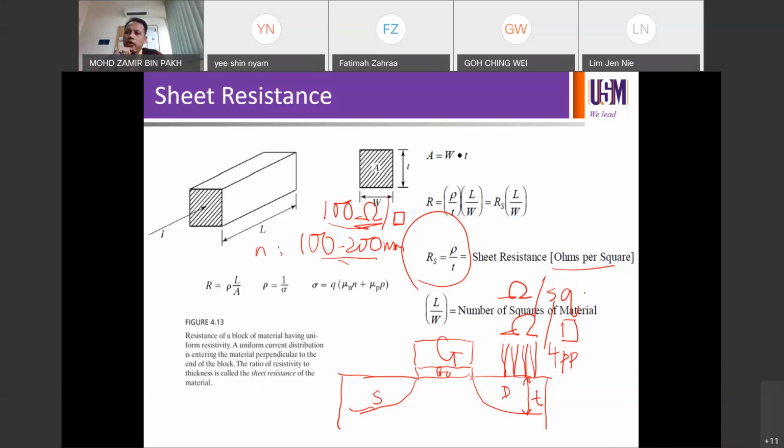If you get a very high conductivity in that layer, you want to have a very low level of sheet resistance, so the resistivity of the layer is also low and the sheet resistance is also low. What low sheet resistance means is that your carriers, electrons in this case, can pass through the channel with minimal resistance.